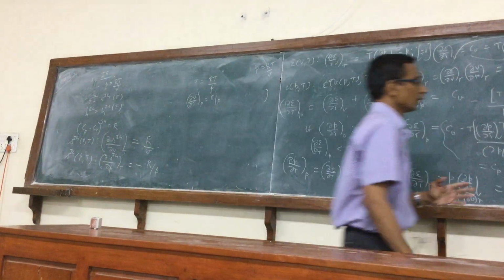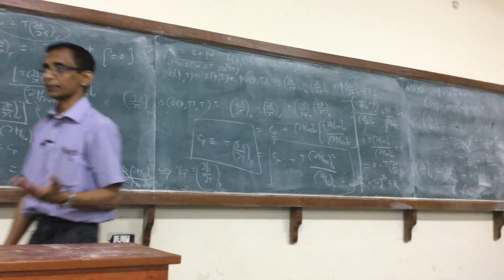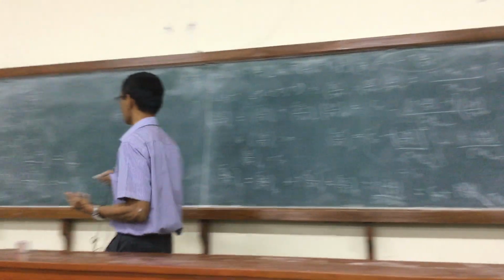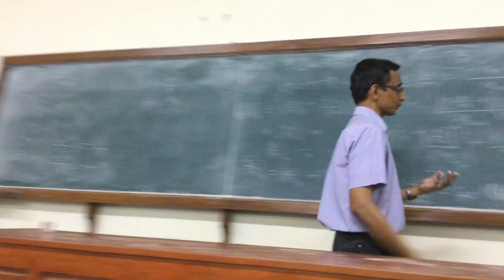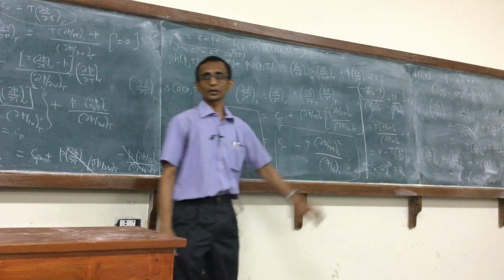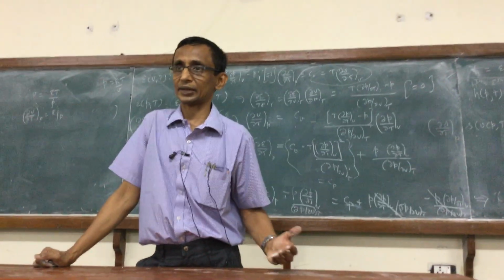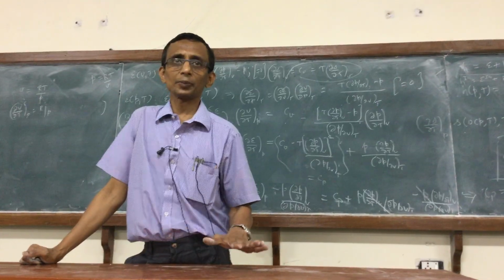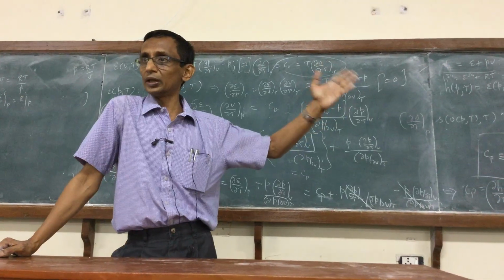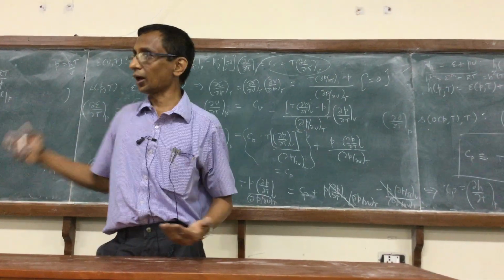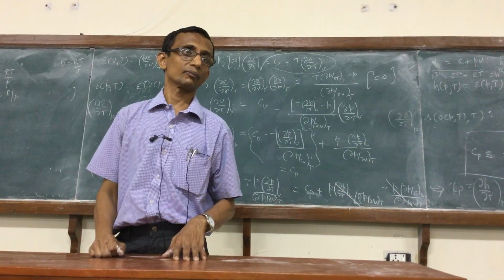So again, Cp and Cv are related to the equation of state that is valid for any substance. This is a generalization of this. You can ask, Cp minus Cv is R for the ideal gas. What is it for a general substance? This is given by this somewhat complicated looking expression that simplifies considerably for the ideal gas. If I know Cv, then I pretty much know Cp for the ideal gas. For any other substance to calculate the relation, we need the information about the equation of state, but not for the ideal gas. It's a universal constant, which means the same for all ideal gases.